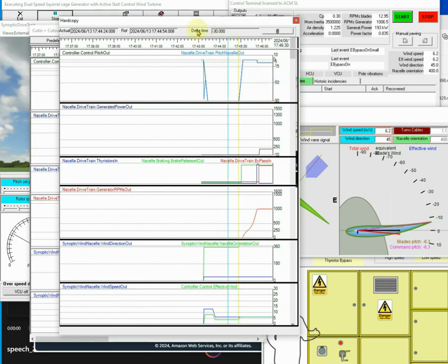Observe the hydraulic braking system sensor, green signal in the third strip recorder, is not liberated immediately. Rather, that release happens when the pitch angle arrives at some value. That has to do with the controller's algorithm to test that the hydraulic system does perform properly. When the brake is released, the blades start rotating. Look at the acceleration of the drivetrain RPMs.